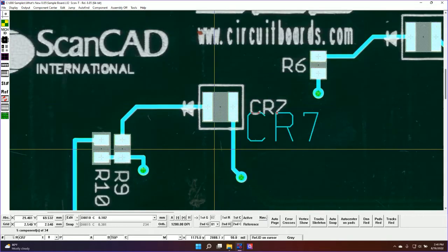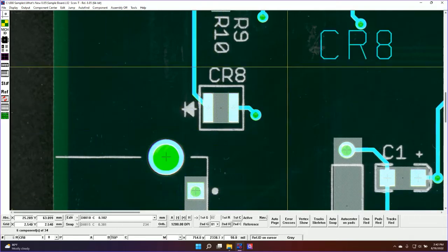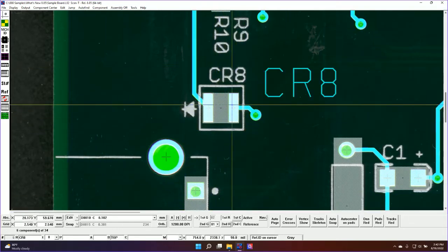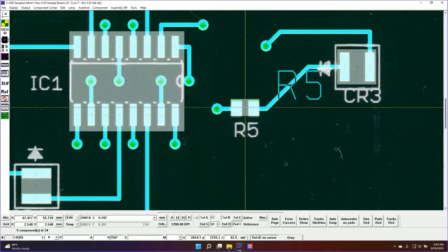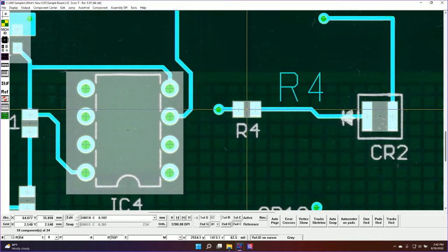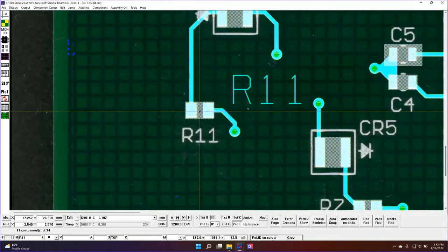You can see that this goes really fast because they're all the same theta. They're all the same angle. So I don't need to keep looking down here and cross-referencing that. I know that they're all the same because I sorted them that way. So all I really need to do is check the component ref ID, which is right next to the silk screen. Very easy for me to tell.